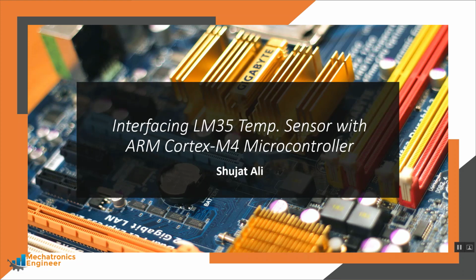LM35 is a precision integrated circuit temperature sensor whose output voltage varies based on the temperature around it. Since the output of the temperature sensor is analog voltage, therefore we will be using the ADC module of the microcontroller. So let's start.